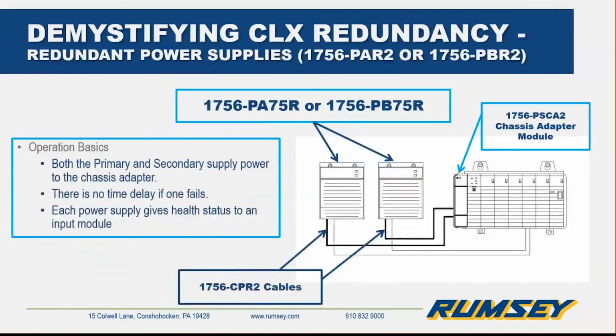Well, a lot of people don't get this because they have the redundant racks. So it really comes down to whether it is a specification where they have to have redundant. Very often, the spec we looked at the other day said everything has to have redundant power supplies, even with redundant controllers. Power supplies are probably one of the most likely things to wear out and fail. So yes, if you have the budget for it, I would put a pair of these on each host for the redundant racks.